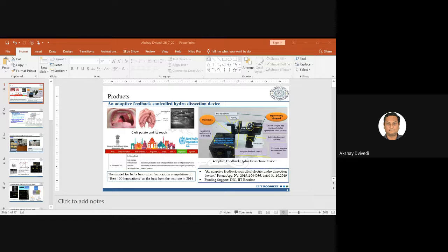So if we add, let's say, grinding action, which is basically a mechanical action, to the electrochemical discharge machining, we can do something about that passivation layer. Now, if somebody wants to know more details about this, I will simply request, please search electrochemical discharge machining in my name. You will find multiple publications in this regard. But yes, there was an issue and there is a solution that was provided.